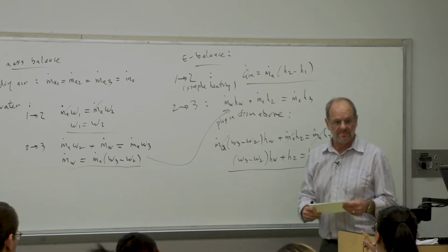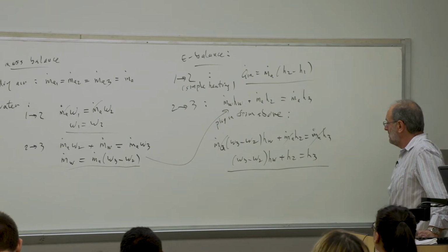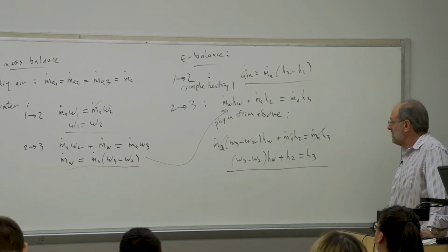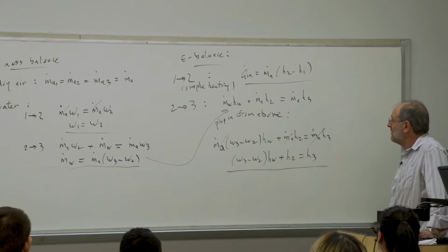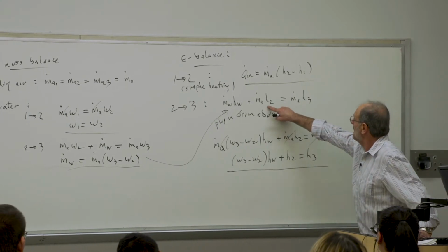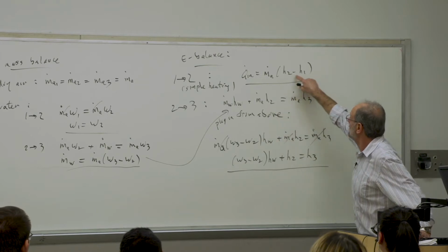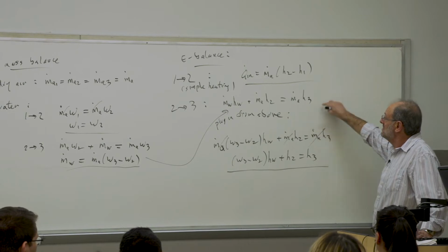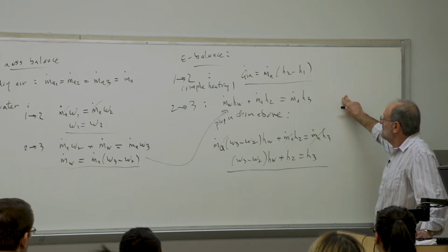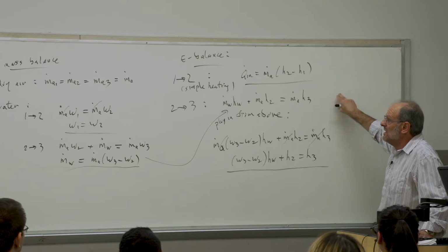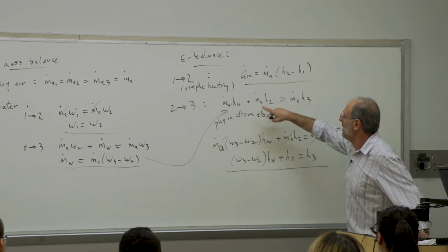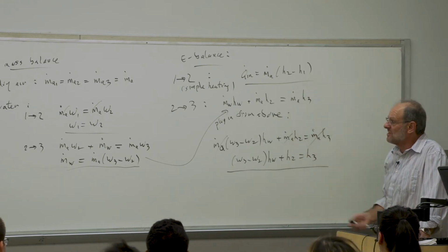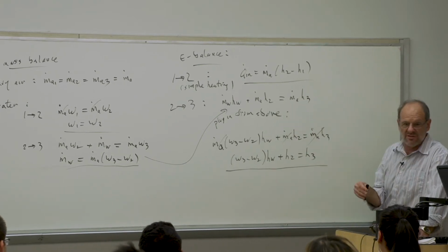In the energy balance equation, how are we taking into consideration the energy that is brought by the water vapor in the air initially and the final water vapor? Well, that's what the H1, H2, and H3 terms are all about, right? But isn't that the energy for dry air? No, no. These are mixture enthalpies. H W is obviously just water, but H2, H3, H1, those are the enthalpies of the mixture, but per unit mass of the dry air.